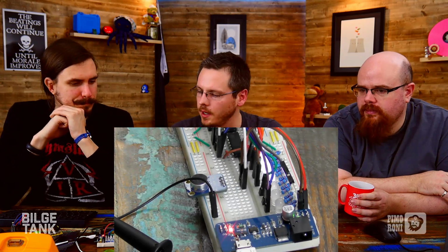interfaces. SPI is nice because you can drive more than one device at a time. It has a chip select feature. Okay. You can kind of round robin different chips. If you need more than 4 channels, you'd probably buy the MCP3008, but you could in principle put 2 chips down and use chip select to switch between which one you want to talk to.